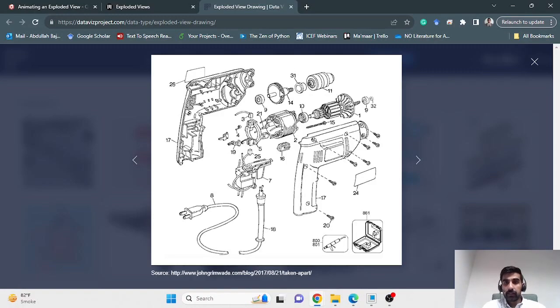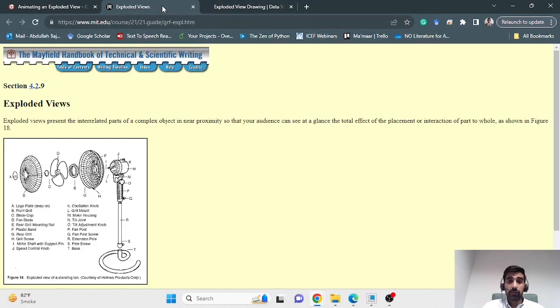These components would again be coaxial. They might be a part of this sub-assembly, or they might be a different sub-assembly, but overall we can get a gist of how various components are assembled in a sub-assembly. If you want to provide more details about how to assemble things, you can add connection lines, which will tell you how to assemble things together, and we'll look at that as we start making exploded views.